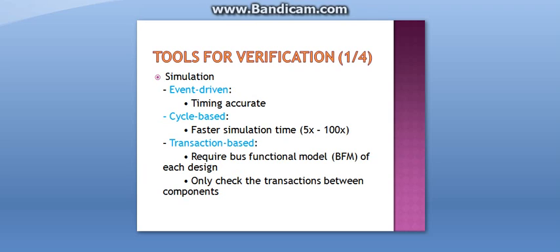There are a number of verification tools. Simulation is one of the tools for verification. It contains simulators like the event driven simulator. It is for accurate timing. Second is the clock-based simulator. It gives faster simulation time. Third is the transaction-based simulator. It requires a bus functional model of each design. It only checks the transactions between components.